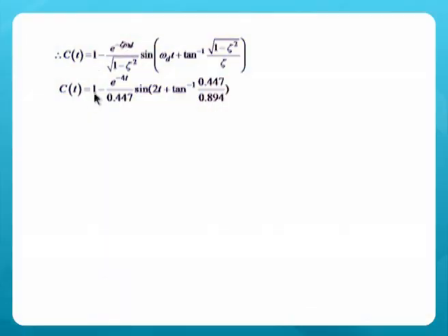It includes the steady state value of 1, and this remaining part is the damped oscillations, which are going to die as time approaches infinity. So the total time response consists of two parts, the steady state part 1, and the transient part which is not going to be there for a longer period. Practically 4 to 5 time constants is sufficient for damping out these oscillations.